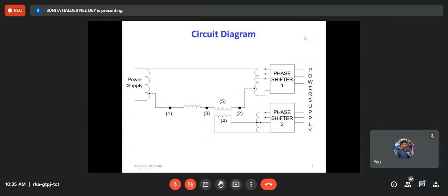So here see terminal 1, terminal 2, terminal 4. We are taking all from the AC supply, and we want to make the phase angle difference using the phase shifter. So it is the same source, but in a practical power system, at terminal 1, terminal 2 and terminal 4, there will be entirely different generators. So their characteristics will be different, their voltage magnitude and angle will be individually controlled. So their control range will be more.